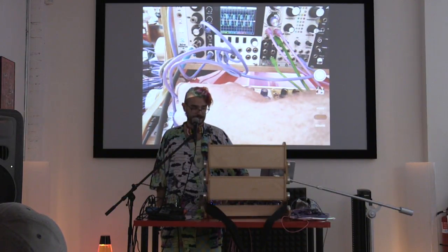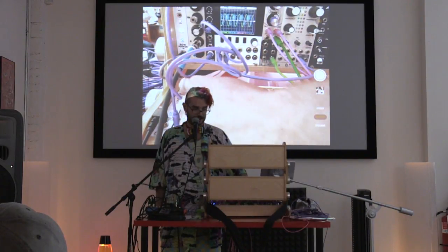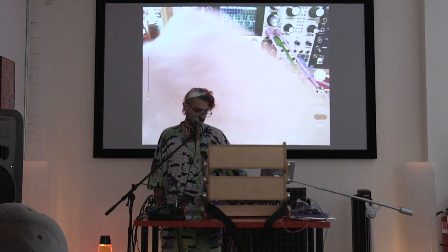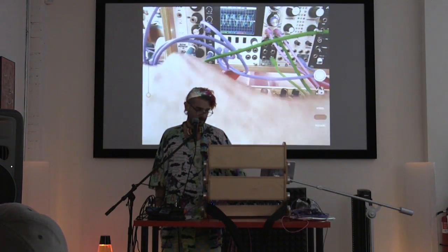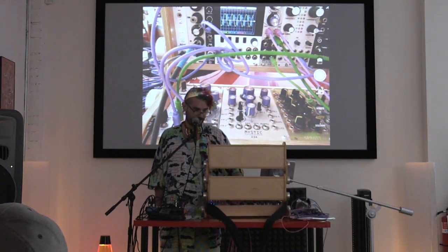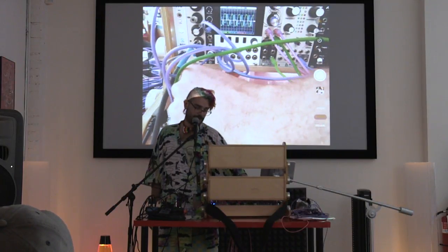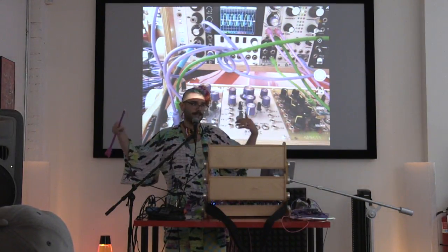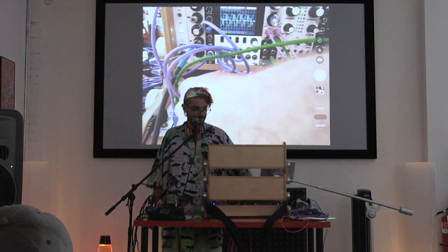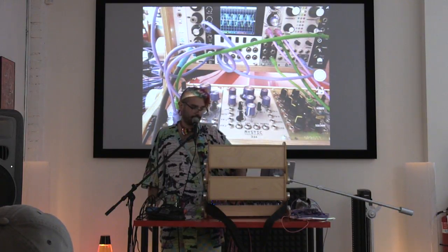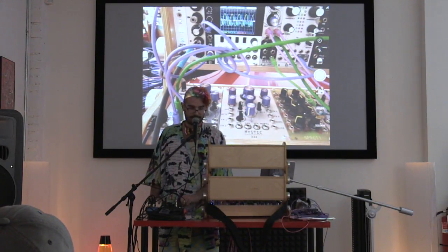This control is bias, which just literally adds a second waveform to the input, but when you modulate it, it will sort of mess with the way that the wrapping is happening. So if I add something in, we've got an LFO going in, and you can see even though it's very slow, it makes it difficult for the wave wrapper to decide what point it's wrapping at. So it's just another way to add some chaos to the signal.